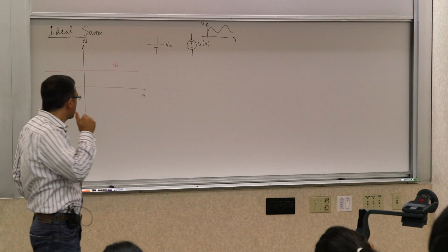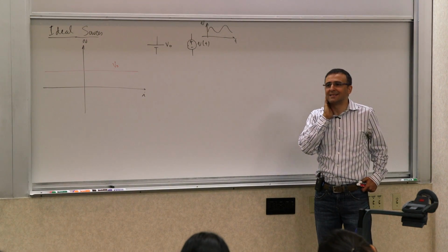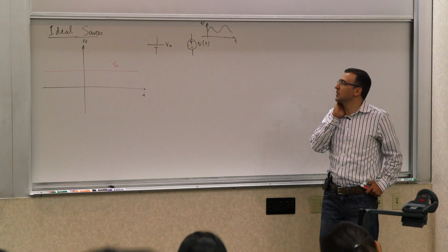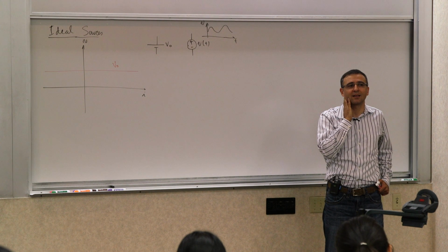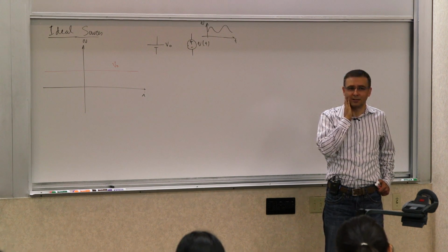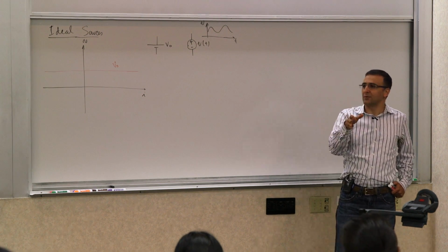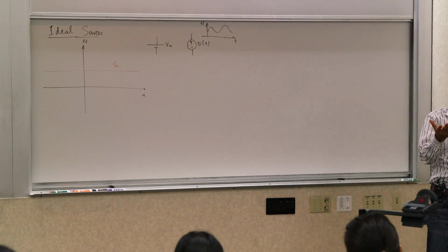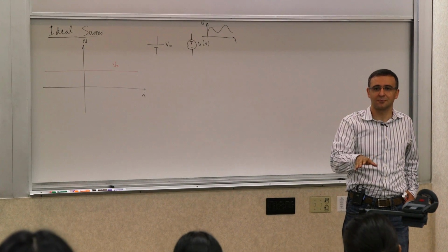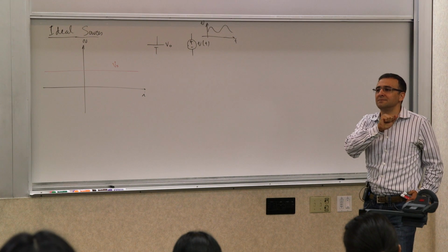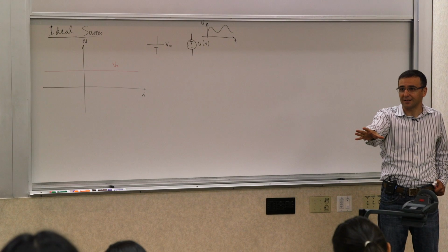The other thing, so let me ask you this question. What is a voltage source? A constant voltage source whose voltage is 0. So if V0 was 0, what is that? Think for a second. A wire, you say. Well, yes, a wire is a good way to answer it. Formally, if you wanted to find it, it's called what? A short circuit. No, not a ground. A short circuit. Ground is something else. We'll get to ground. But it's a short circuit. Or wire. Wire is a good way to think about it.